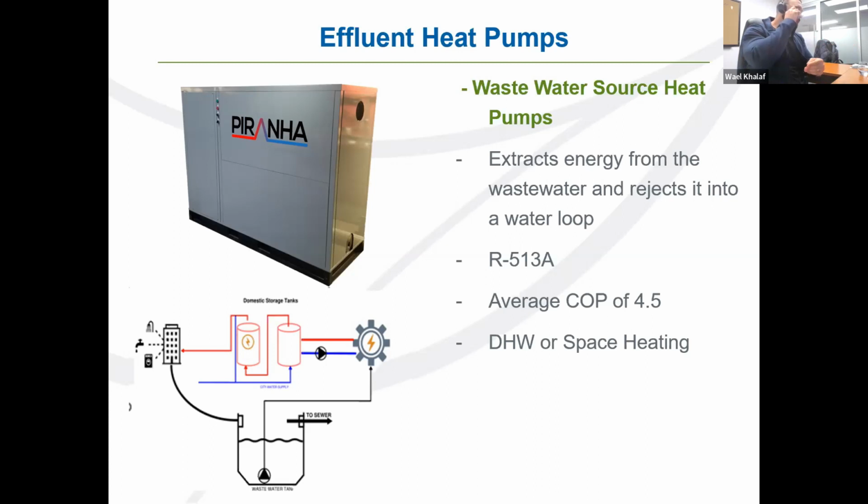And just, without getting too much into detail, because this is a presentation on its own, inside the Piranha, the wastewater is completely decoupled from the hot water or domestic hot water by a double wall heat exchanger on one side and a full refrigeration cycle inside. So you have wastewater, refrigerant, double wall heat exchanger. So obviously there's no contamination, or not even close to it. And it's a completely sealed and vented system. So if you have this in your mechanical room, it doesn't smell at all.